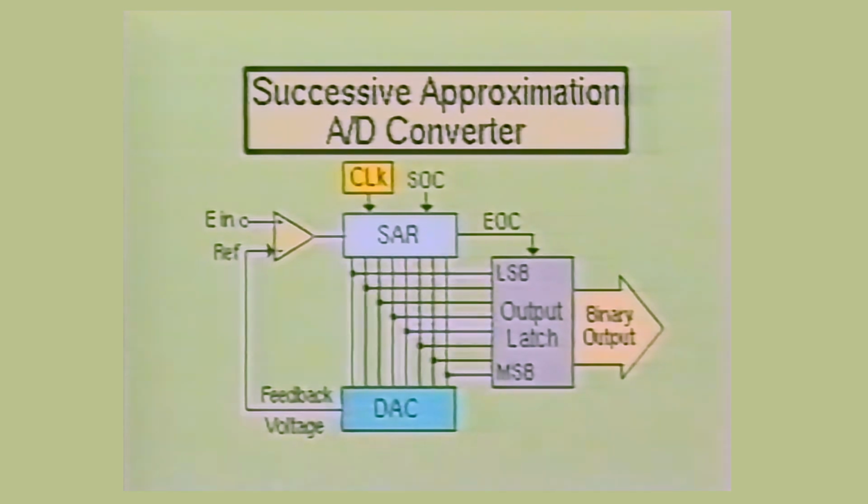Even though the successive approximation converter operation is more complex than the 3 previous converters examined, it is perhaps the most efficient type of AD converter presently available. As you have seen, this style of converter is capable of extremely fast conversions at high resolutions. When utilizing this technique, 12 bits of resolution can be processed in 10 microseconds or less.